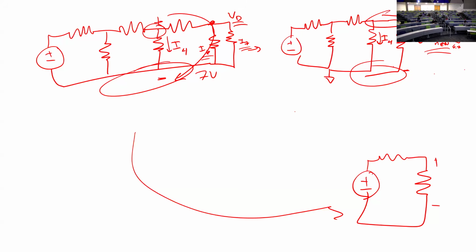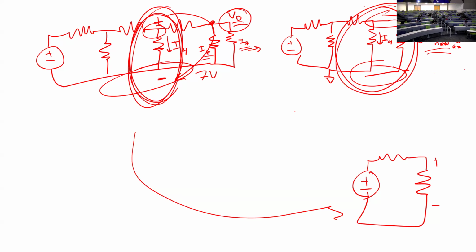So say I do know this voltage. I'm now missing VD because that node got erased when I stepped here, right? So I know that from here to here I have 7 volts. And going in, I have some resistor and some second resistor. And this is VD. Here we would use a voltage divider.